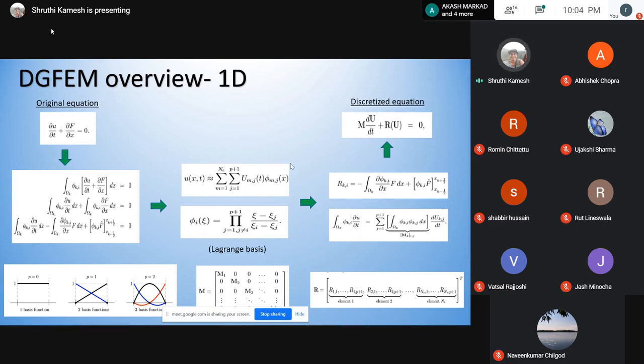For the higher order terms, you would need higher order time stepping. For finite volume, for example, which is basically p0, it looks at just one value for each element. For that, I can use a simple time stepping, and it should be very stable, because I'm using a very simple order in space, so I can use a very simple order in time. But as I go higher, I run the risk of my solution not converging, or becoming unstable, because my discretization in space and time are not compatible. Again, I hope that made sense.